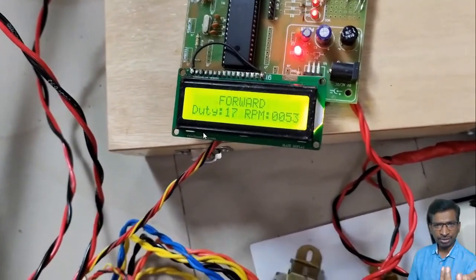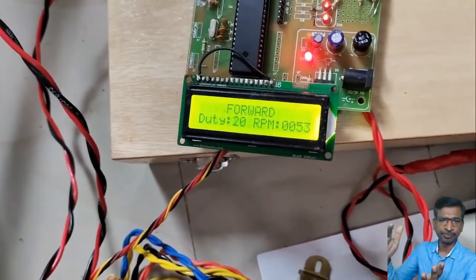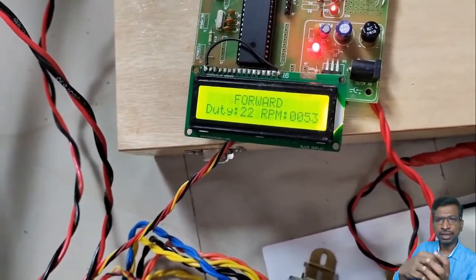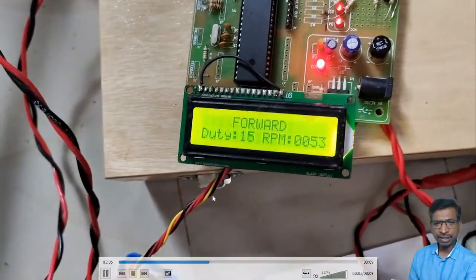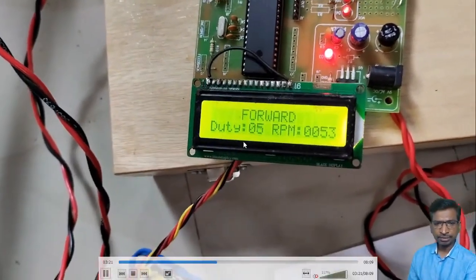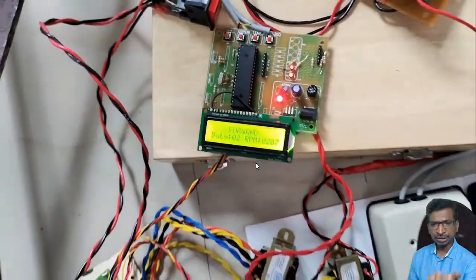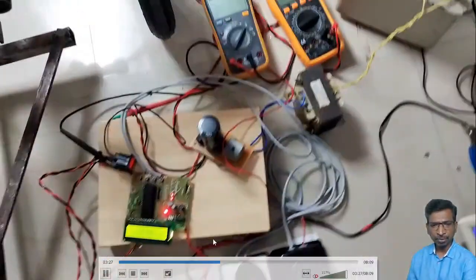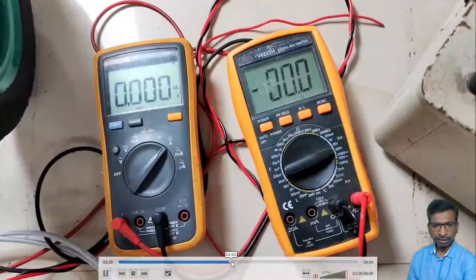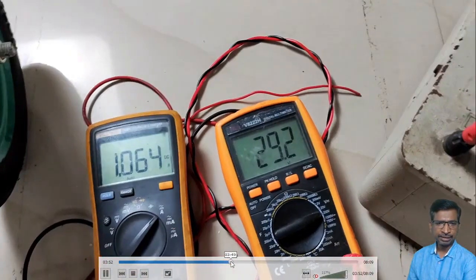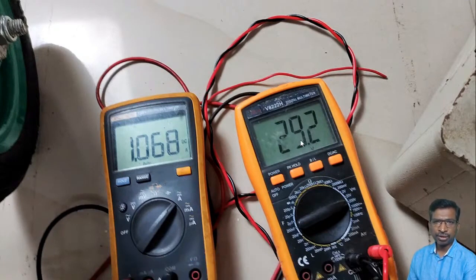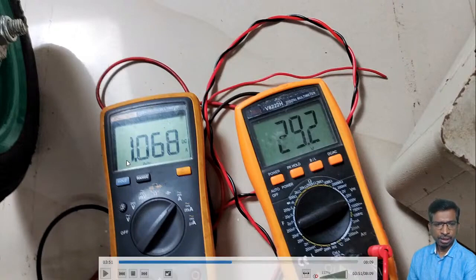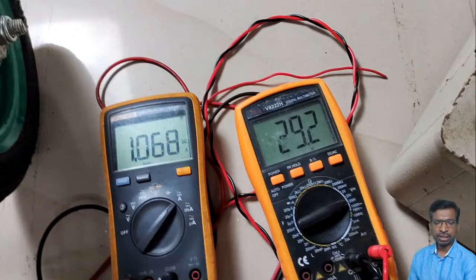what is acceleration? Nothing but you just increase the duty cycle. When you increase the duty cycle, the voltage across the terminals of the motor increases. Now we are increasing the duty cycle. Similarly, if you apply a brake, then the duty cycle will approach 0. And see here the initial current of the load. Initially the load has not been applied, so it shows 29 volts, but the motor will draw 24 volts only, and 1 ampere is the initial current because the motor is already powered up with the gear.